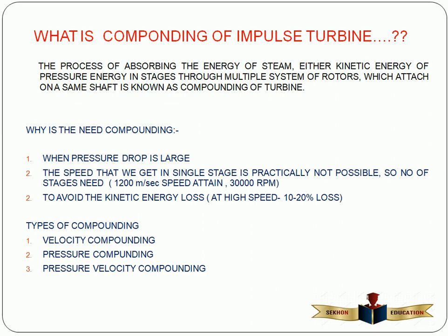Second, when we change pressure energy into kinetic energy, it produces a tremendous amount of kinetic energy. However, practically it is not possible to attain such a high amount of kinetic energy in a single stage to impart it to a single moving rotor. That's why we need to divide the velocity into a number of stages and also divide the pressure into a number of stages.